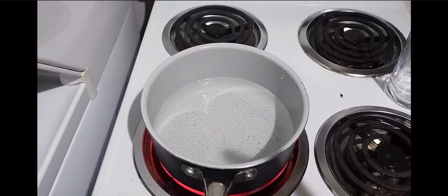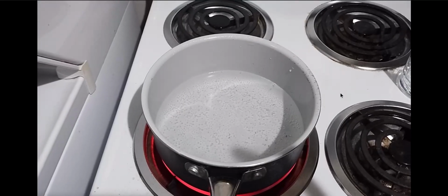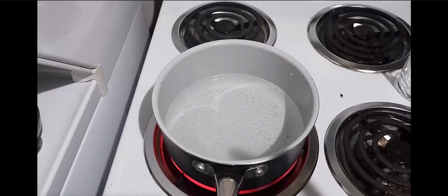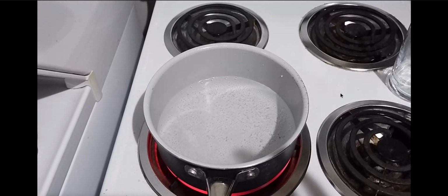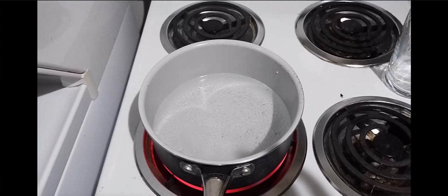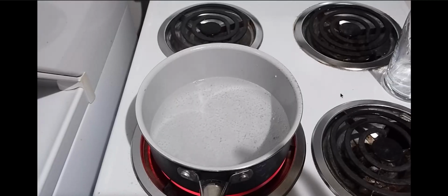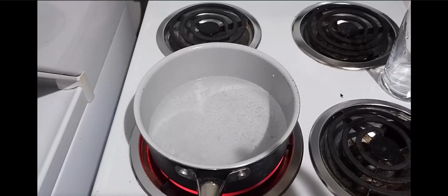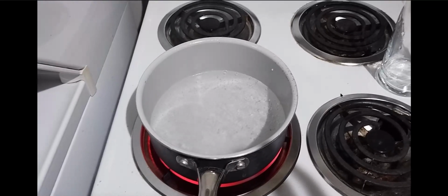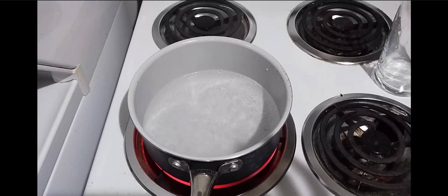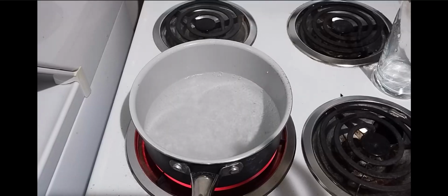So right about 105 seconds, so boil. So anything higher than 212 degrees Fahrenheit will be super saturated steam enthalpy, so we're above 212. So we'll say 105 seconds to heat up 1 pound of water from an initial temperature of 50 degrees Fahrenheit to a final temperature of 212.